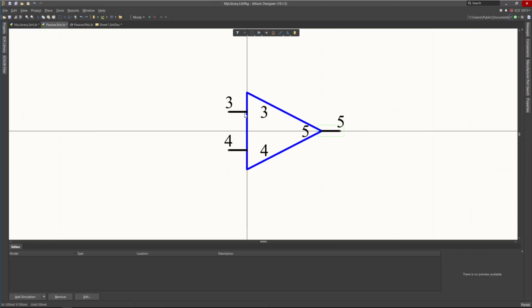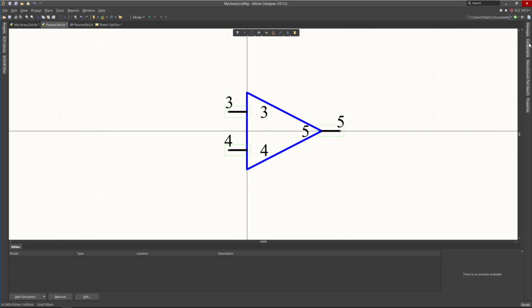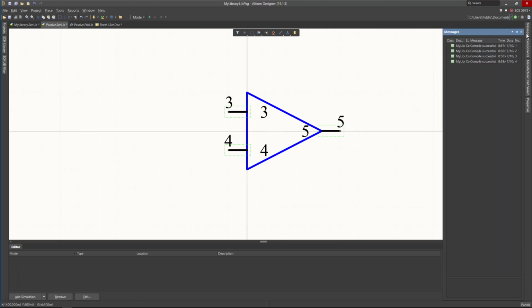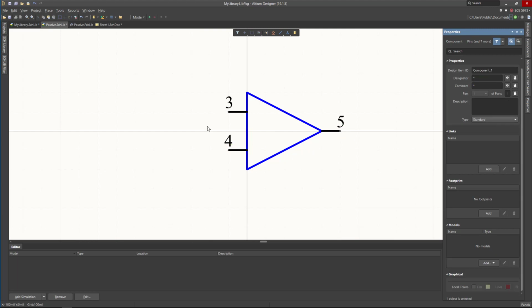Now you don't want to really show the comment in here, so you can hide the name of that pin. I will show you an example where you show the pin, usually for an integrated circuit like a microcontroller or stuff like that. So you can hide the pin. You can select all and click on this, it will be hidden.